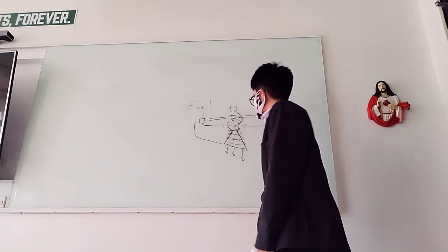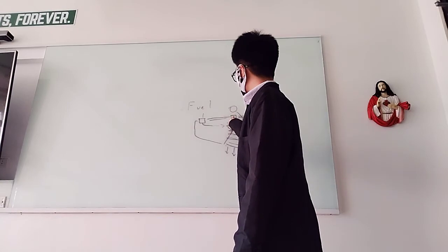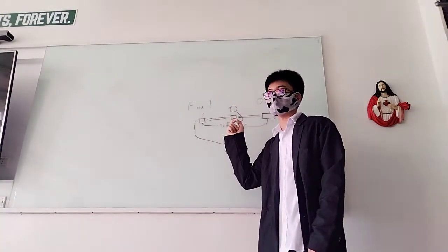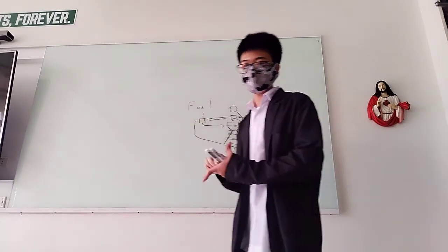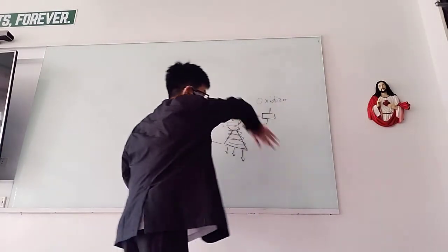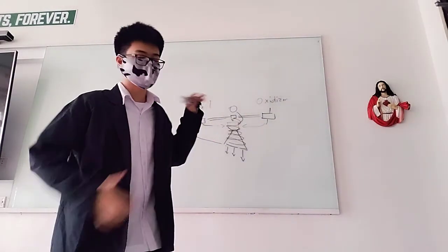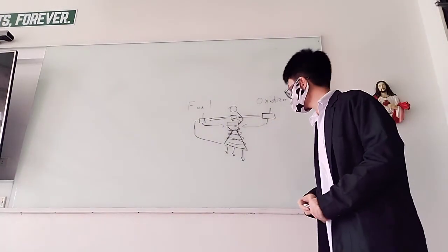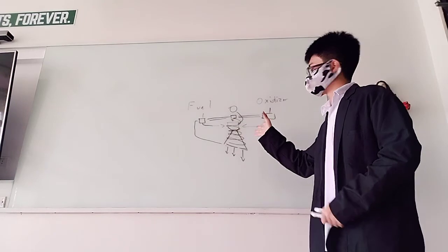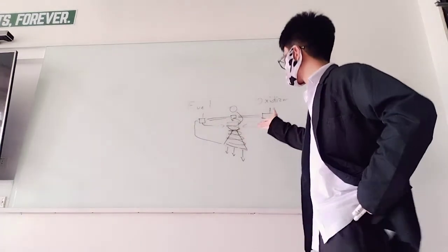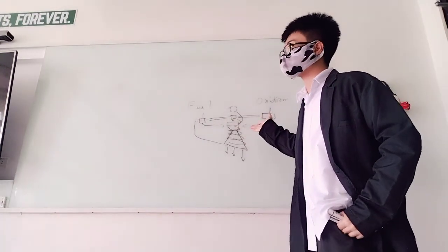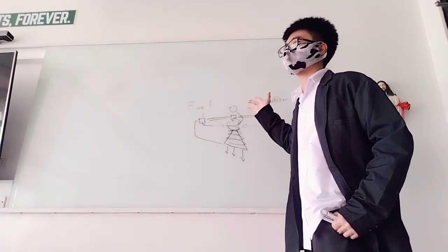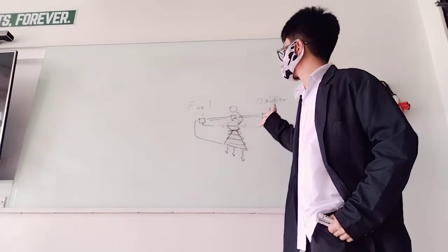Okay, so part of the fuel is put into this chamber and burned with the oxygen. So this is a small mini combustion chamber that makes the pumps go. And this stuff is probably just dumped out or put directly into the engine, but that would cause some problems because of soot and some clogging. So that's the basic concept of what's called a regeneratively cooled, partially staged combustion engine, I believe.